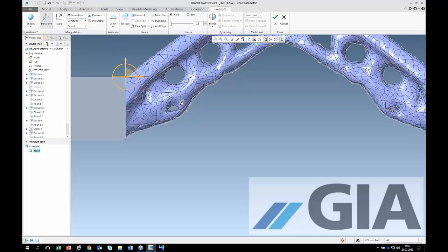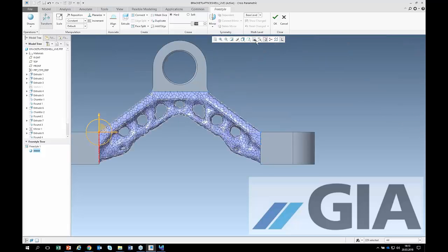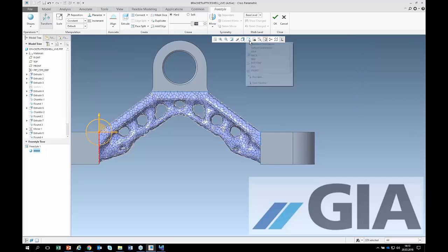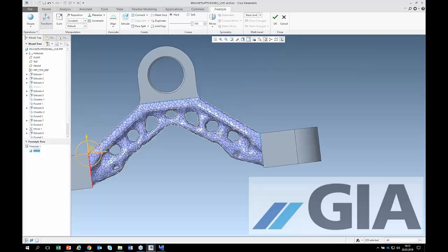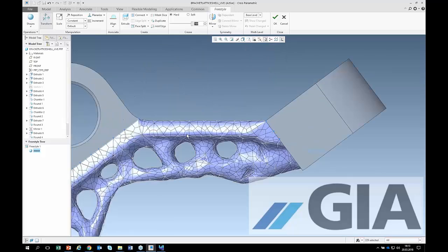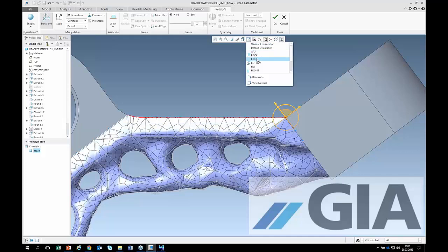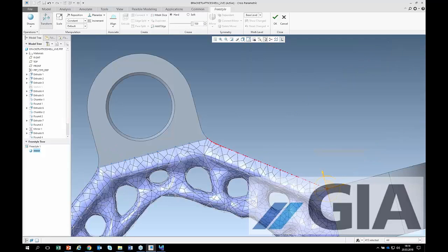Okay, that's done. Let's go for another view here. Let's take the view AAA. In this view AAA, this line is horizontal. So I'm selecting those guys here. I'm making them sharp. And as a last area, I'm switching to that view here.